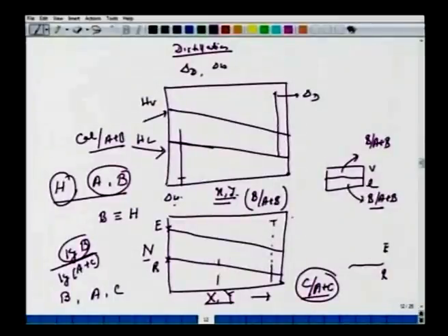You will look for this delta point depending upon the reflux ratios in the case of extractions. From the reflux ratios, you can get this F connected here, and one can find again a tie line connecting with this, another tie line connecting with this, etc. So extraction with reflux is quite uncommon. It's not very popular. It's very difficult to maintain a constant reflux ratio in an extraction system.